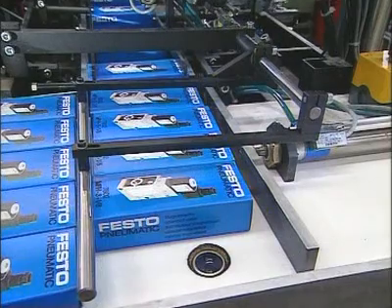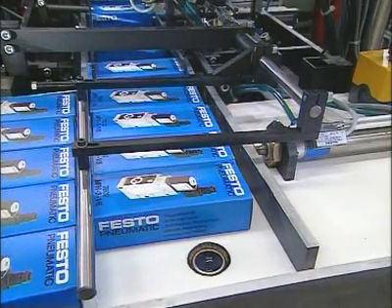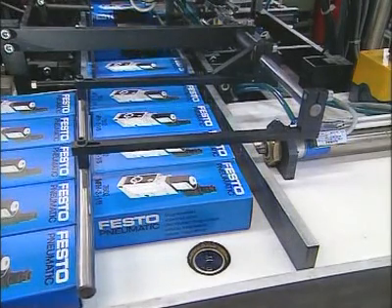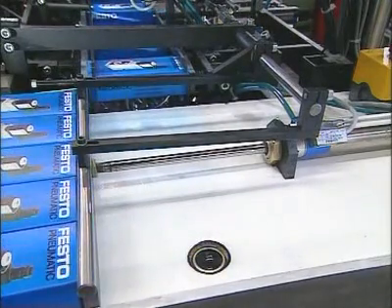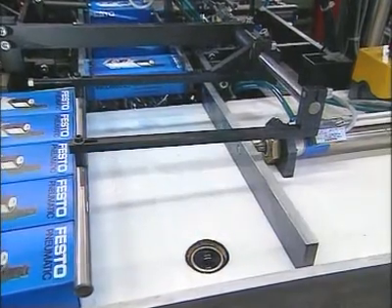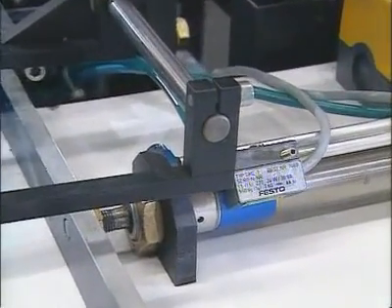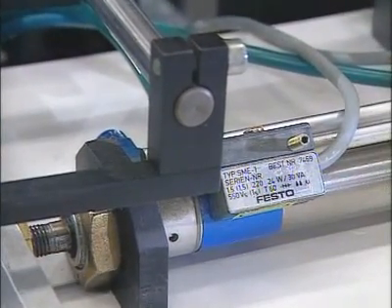The function of this electropneumatic slide unit is simple. When the optical sensor signals that 5 packages are present, the piston extends. When it reaches the extended position, the valve is reversed and the piston retracts. As only one condition needs to be fulfilled for each action, the valve can be directly controlled by the signal element.